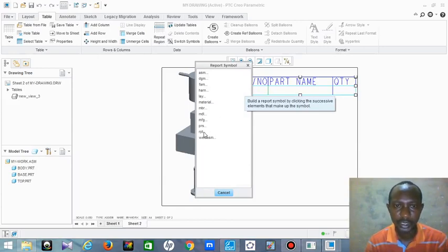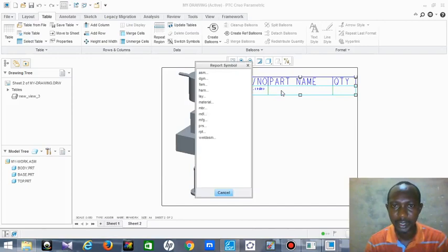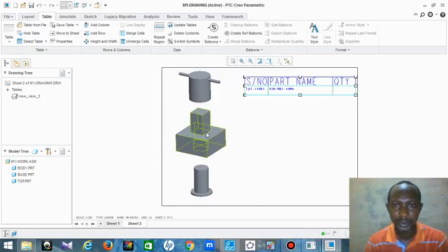Then what you want to report there is you click on report index. You see, to enter the report index, then you double click the middle place. What I want there is I need the assembly numbering, then their names. Just follow the steps. You see ASM, you click on assembly, the numbering, they should follow according to the numbering, then the names of each of these parts, the way I name them in my parts mode, they should come out here like that.